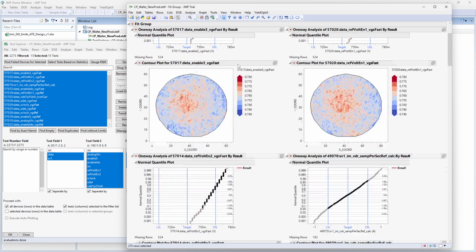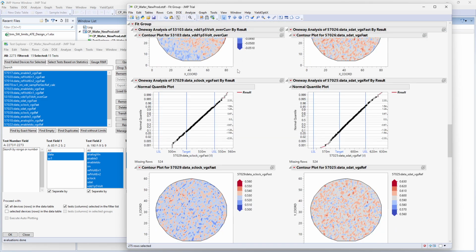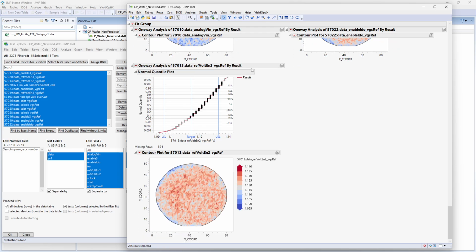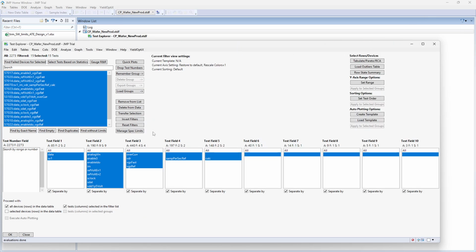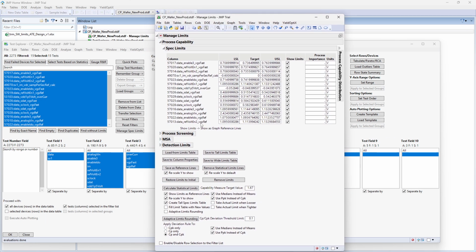In situations where product results respond to increased process variability or changes in test conditions, adapting these limits may be plausible. Test limits can be accessed easily through the Manage Spec Limits button available in Test Explorer. Clicking this button opens a window that lists the tests, current limits, units, and multiple options, greatly simplifying the process of limit adaptation, even for thousands of measurements, by utilizing calculations based on a target process capability index.